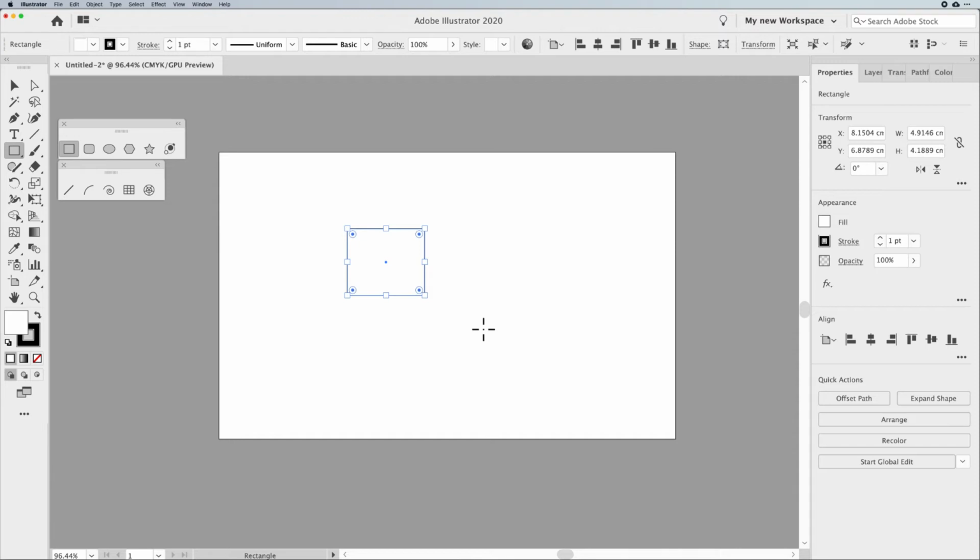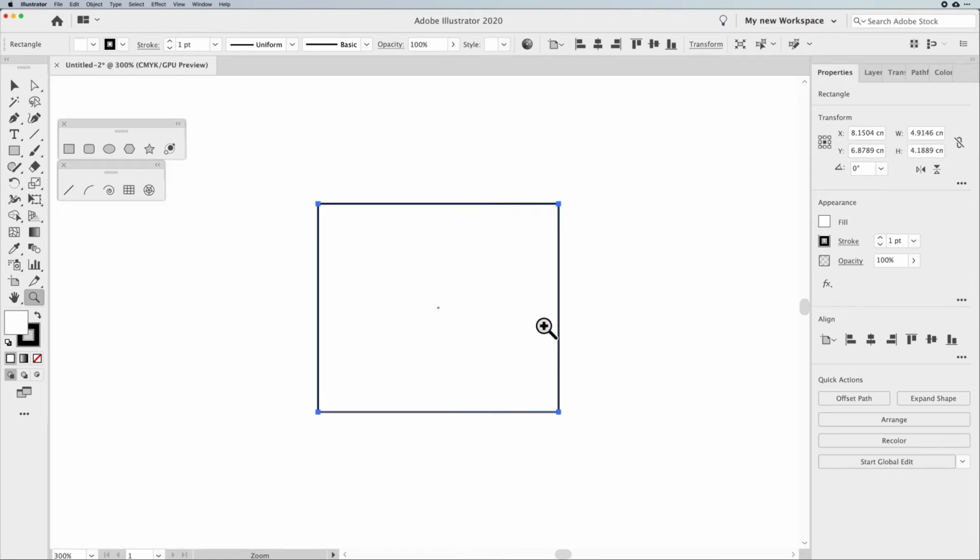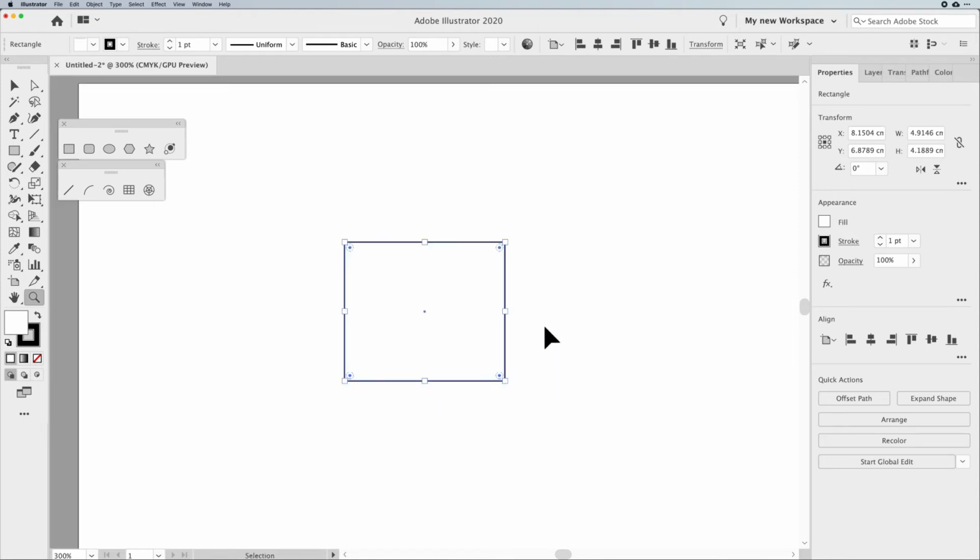Yes, it is. Next is going to be the zoom tool. Zoom tool right here, the letter Z, absolutely. How to use the zoom tool? Well, I see a lot of people use the zoom tool by clicking and clicking and clicking and clicking, and their screen bounces all around. And the reason why is because every place that you click, you have then zoomed in, but that click point now becomes the center. So if it's going all over the place, it's all you. Now, clicking multiple times here is truly a waste of time.